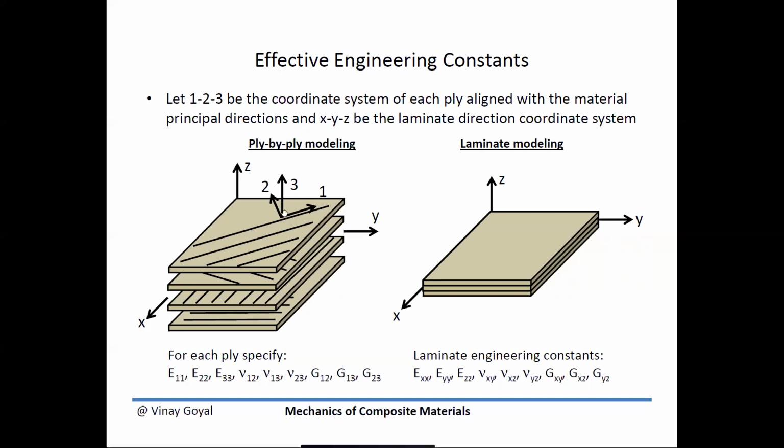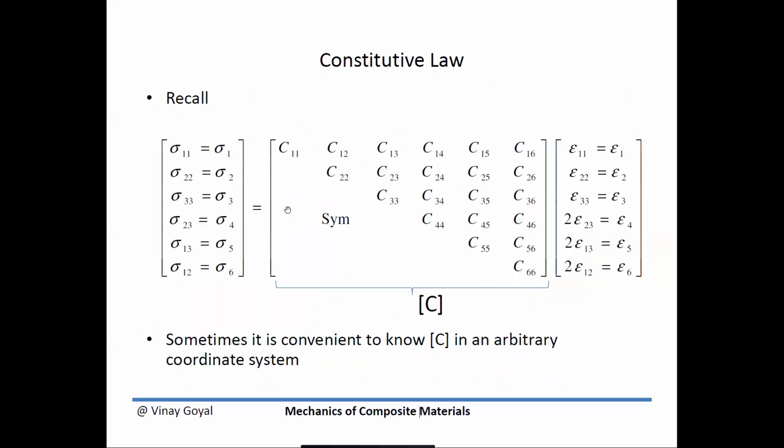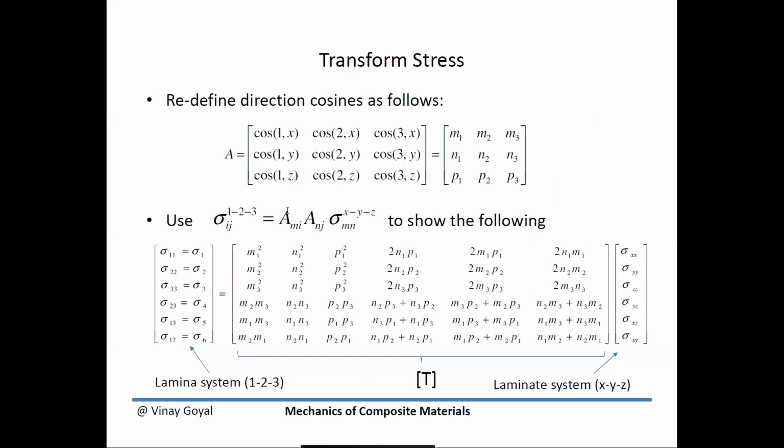But as long as the 1 axis rotates, the 2 axis will rotate too, because the 1 and 2 are 90 degrees apart. As a consequence, there's only one angle that varies. As a consequence, finding the direction cosines for every single lamina is very straightforward to do.